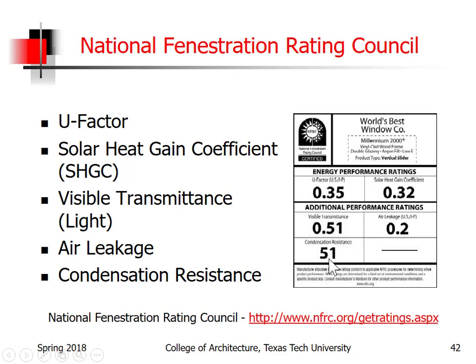And then condensation resistance has to do with its resistance to condensing on the interior. And this is an issue mostly in cold climates, especially where there is a lot of humidity or moisture. If it gets cool enough that the dew point is reached, you can have condensation on the interior of your glass. Here in Lubbock, Texas, or El Paso, that's not too much of a problem, because once again, we don't have a lot of moisture or humidity.